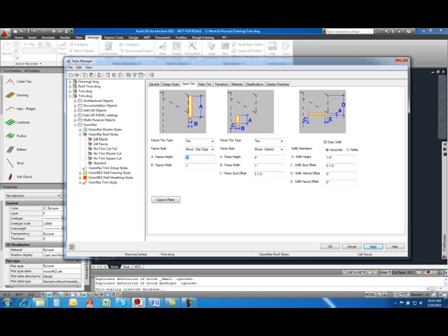But instead of 1 inch, the total width of my new trim is actually 2 inches, because that little bump out is actually 2. And that's an important factor to remember, what the total extent of your trim is. If you get that a little off, we'll show when we make a custom frieze style that you do need to be very accurate about those numbers. So just on the eave, I'm going to change that from 6 to 2, and as well I'll go on the rake side and do the same thing of changing my wood exterior, making that 2 inches wide,